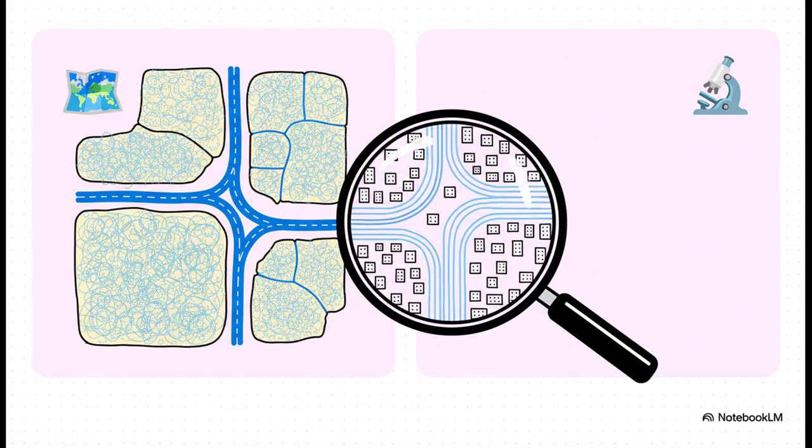First, there's global routing. Think of this as planning the major highway system between our different districts, trying to avoid any huge traffic jams. Then there's detailed routing. Now we're down to the street level, assigning each individual wire to a specific metal track on a specific layer, making sure no wires touch and every single design rule is followed to the letter.